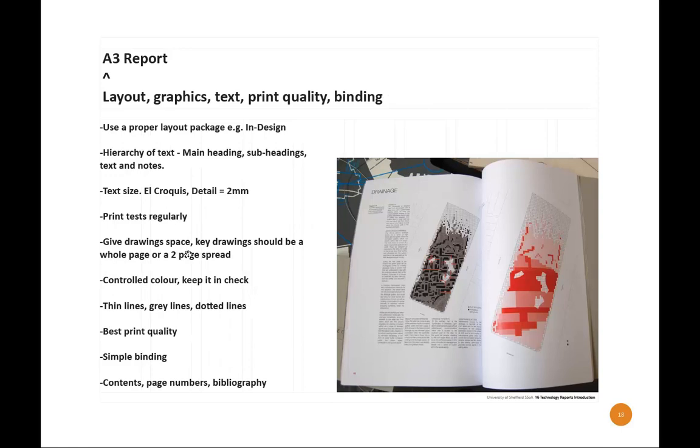Give drawings space. Key drawings should be a whole page or a 2-page spread. Don't squash your drawings in. Absolutely do not overlap drawings. That is disastrous when it happens, when you start overlaying a site plan with something else or a bit of text, almost like you've run out of paper. That virtually never works. So just be wary of that.